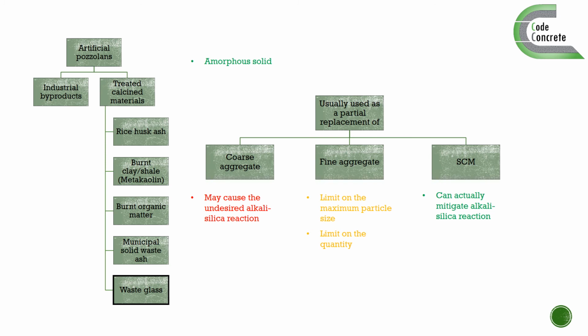Glass powder is considered pozzolanic when used as a supplementary cementitious material in the proper particle size, usually less than 75 micrometers. It is mainly composed of amorphous silica despite its various types produced, such as silicate, soda lime, borosilicate, lead, and aluminosilicate glass.